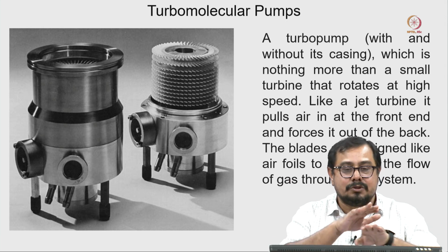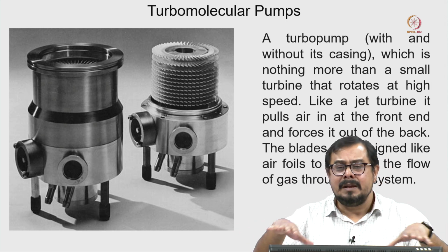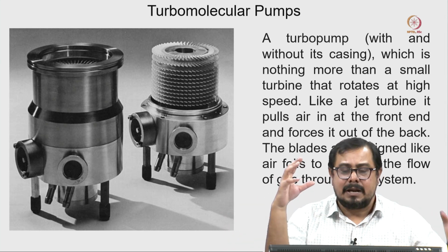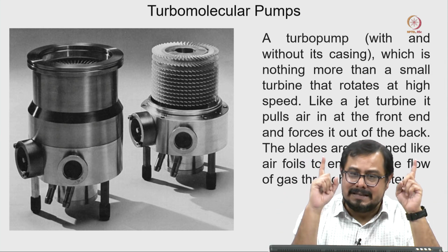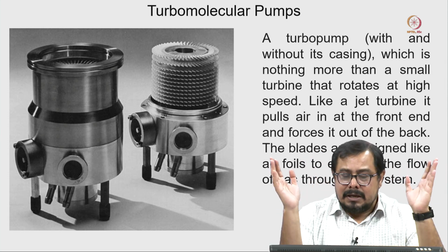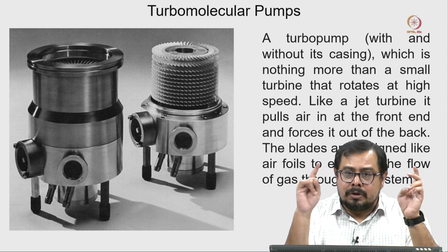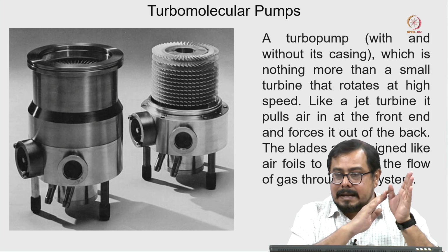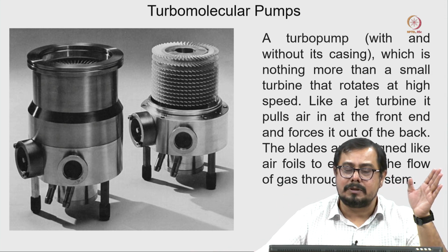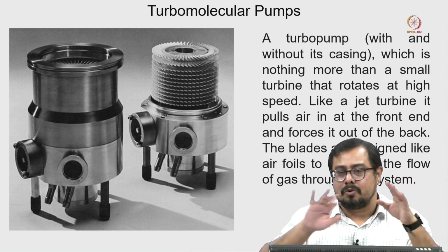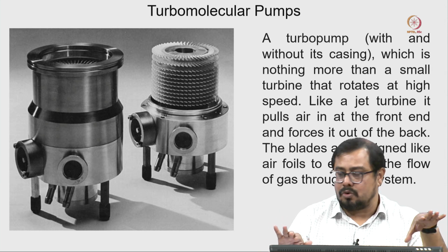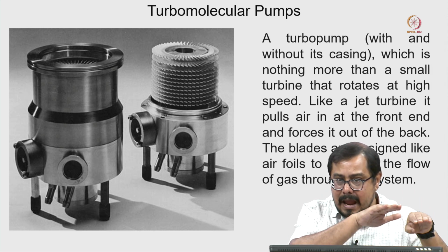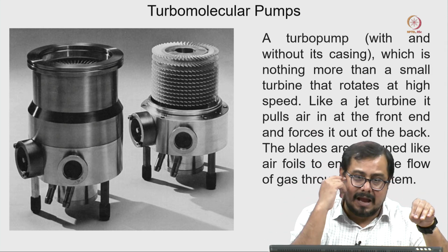So, this pump works from normal air pressure to a very high vacuum. Generally, it is connected where we insert the sample, because that is the one area where we break the vacuum on a daily basis. So, we need a pump system which will start immediately when you insert the holder and throw out the gas molecules, air molecules, from the microscope. That is the good setup, going from atmospheric pressure to a very high vacuum, but